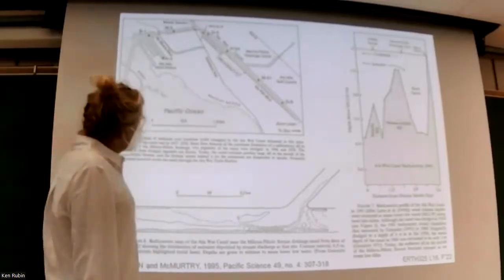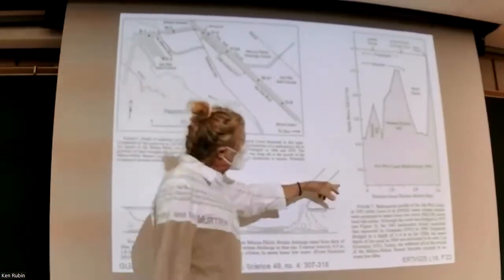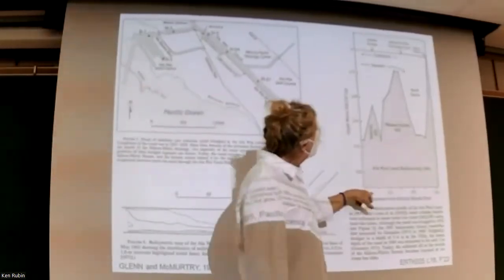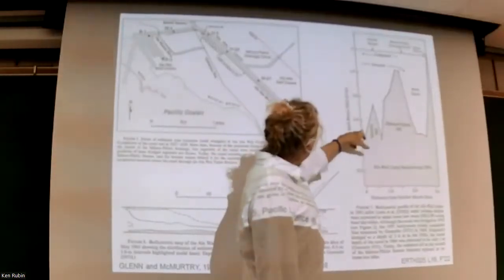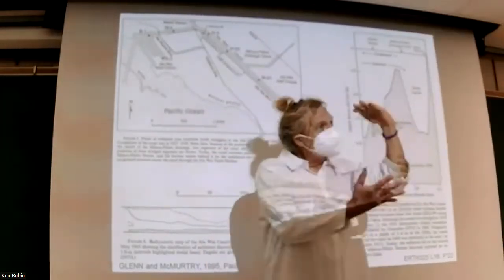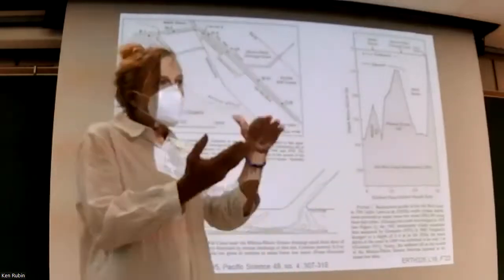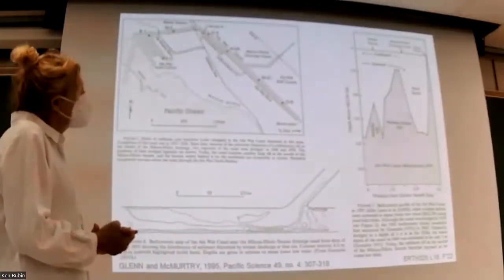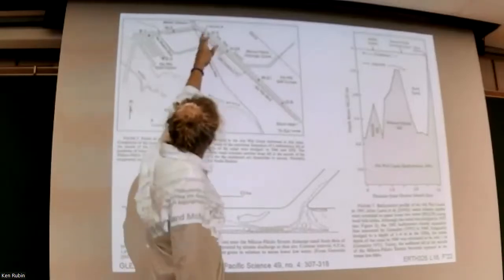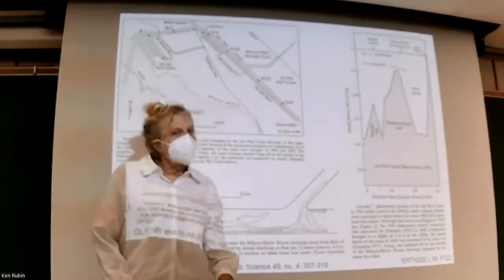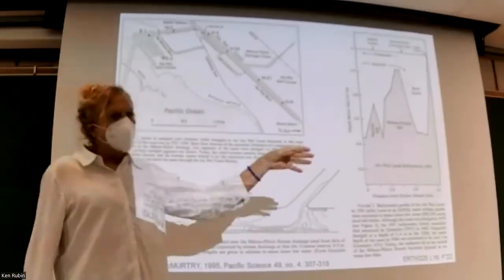And so what you see is, when you go along the canal, this is distance from the harbor mouth, and this is the depth in meters. There's this point where it gets only a meter deep, right? And at low tide, sometimes some sediment actually pokes out there. So what that does is it takes the back basin, everything behind there, and limits the amount of water that can flow back and forth.